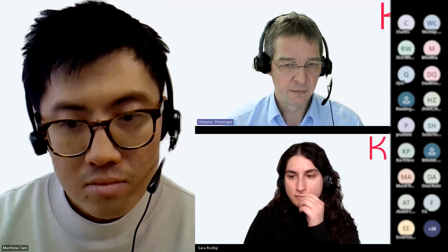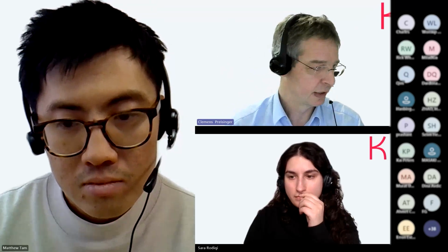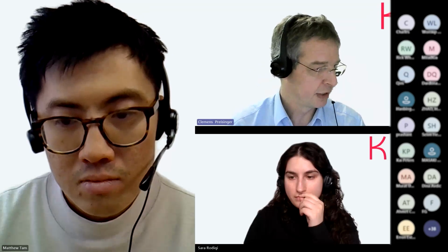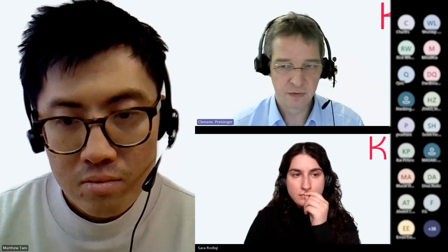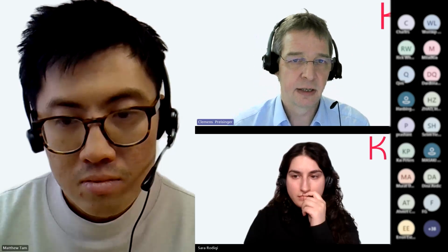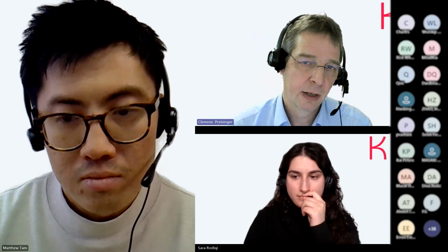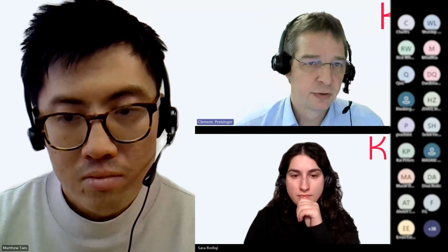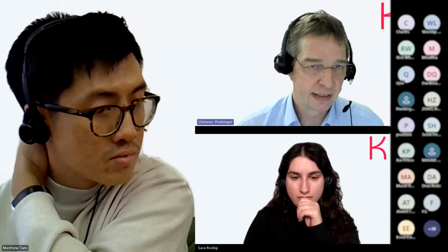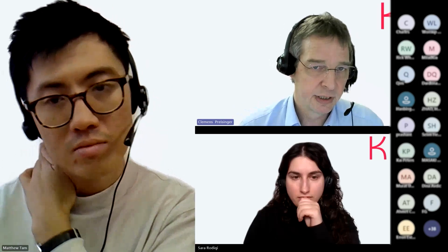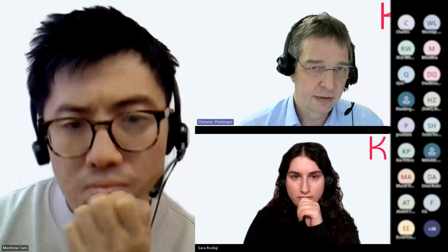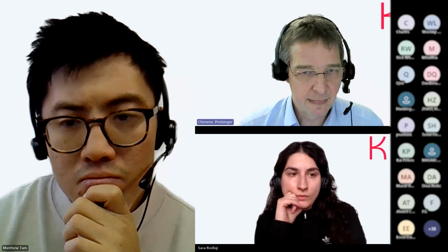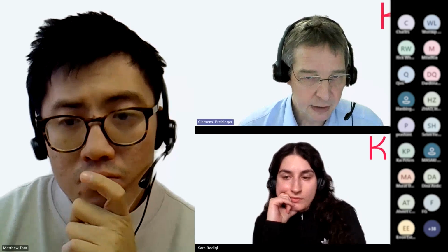But for calculating the stresses, this would give wrong results, and therefore this large deformation option for form finding doesn't allow to retrieve stresses and forces. There is a work in progress version of large deformation analysis, which you can test if you enable here the work in progress versions. However, this, where is it?